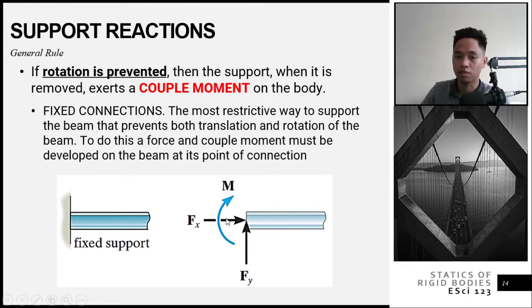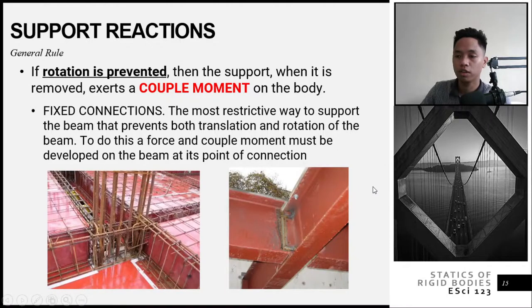So that is an example of your fixed. What are examples of a fixed support? For example, concrete structures. If the beam, the column, and the slab are poured, since it is monolithic, right? It has to be monolithic, meaning it was poured at once. So therefore, if it is monolithic upon pouring, it will provide a fixed connection in our RC structures.